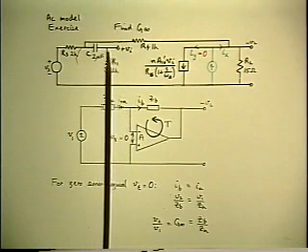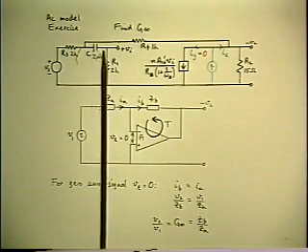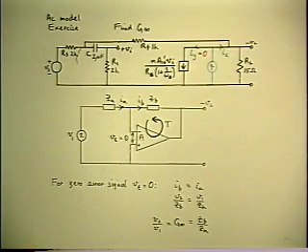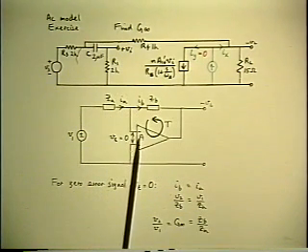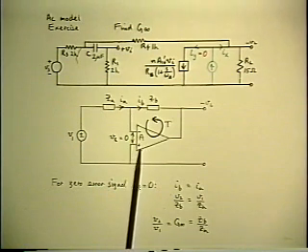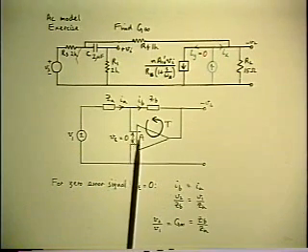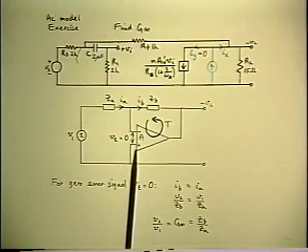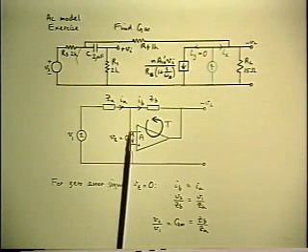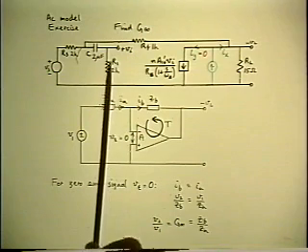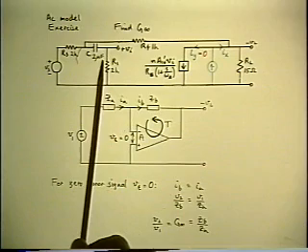The only thing in the circuit we're talking about that's not present in the other one is this coupling capacitor in the R1. But the R1 is in the same position as the input impedance to the forward path. And I already emphasized when we talked about this previously that you make no assumption to do with the input impedance. It doesn't matter whether it's 1 megohm or 1 ohm. The null condition still means that if you have 0 voltage across it, you get 0 current into it. And it's the same thing here.